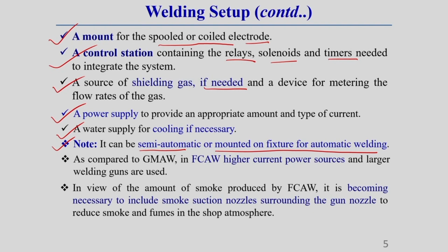Whereas in the SMAW process, that process is generally a manual arc welding process. Why is it manual? Because we can't control the feeding of this electrode automatically. The automatic system depends on automation of filler wire as well as automation of speed. If both filler wire feeding and speed are controlled automatically, then it is called a fully automatic system.